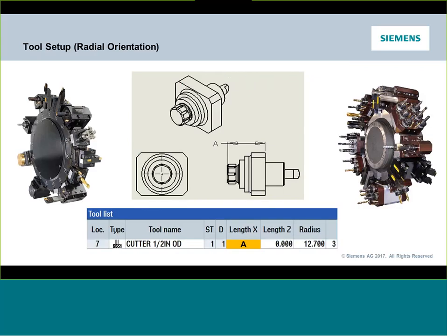So that's the layout of our chucks and the basic layout of our part. The next thing is to get your head around how the tooling is going to be configured. I just wanted to show you a couple of typical live turret layouts. This certainly isn't the only one; there are probably a million different turret configurations when you get to live tool scenarios. This is a BMT style turret, which is pretty common, so I wanted to use it as a base example. It really doesn't matter where your mounting surface is, whether on the periphery of the disc or on the face of the disc.